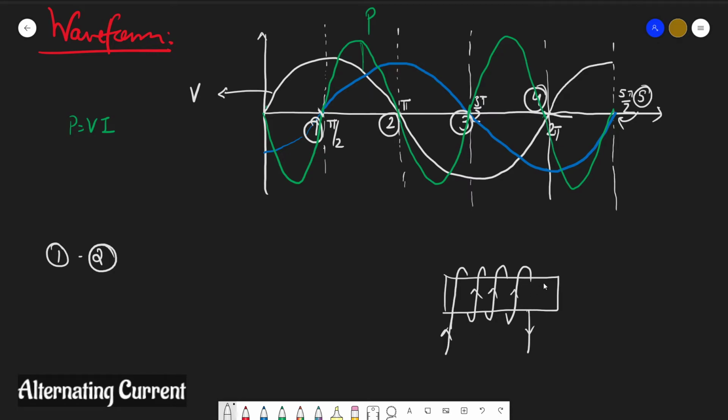So this is down. Anyway, if I see the flux line, according to right hand rule, you can draw the flux line for this. It will be in circular fashion. Let us do 2 of them so that I can do a comparative study. By right hand rule, if you find the flux line, if you curl your fingers, the thumb will be indicating the flux line, so this will be like this only. So this is the direction of flux.